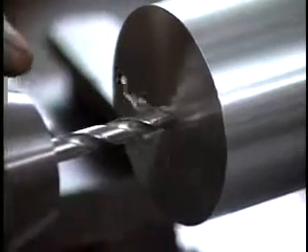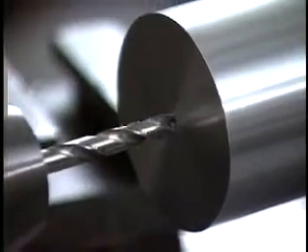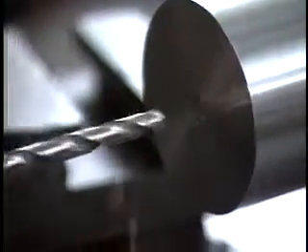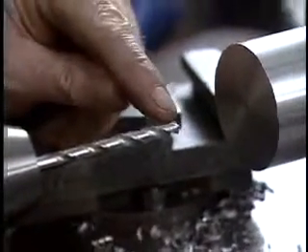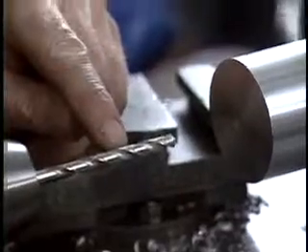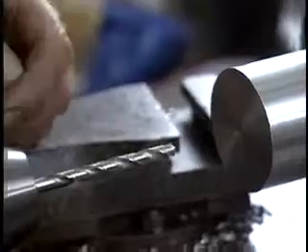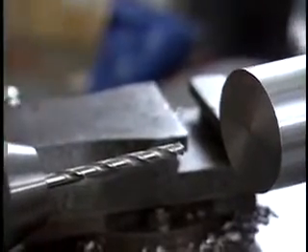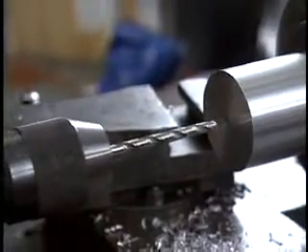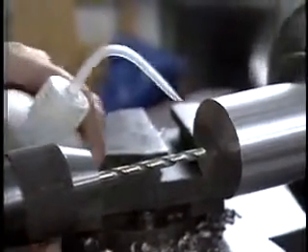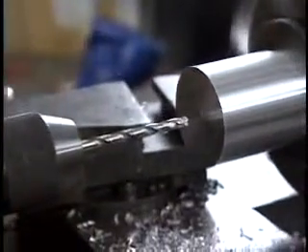You can hear now a squeaking sound. That's being produced by the drill and the chips, because the chips are having a very difficult time riding up through the flutes of the drill and out of the hole, and are starting to bind in the hole and produce heat and chattering. So now that I've drawn the drill out and cleared the chips, before I go in again, I should introduce a little bit of cutting fluid into the hole and onto the drill.